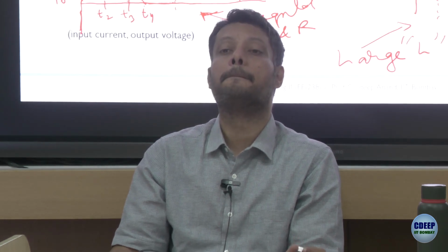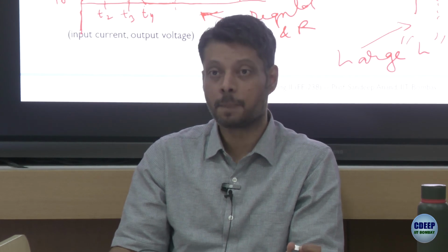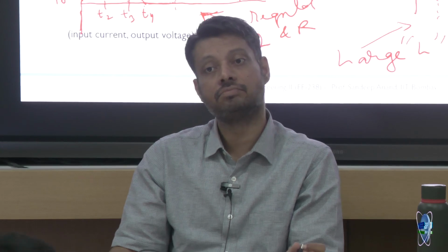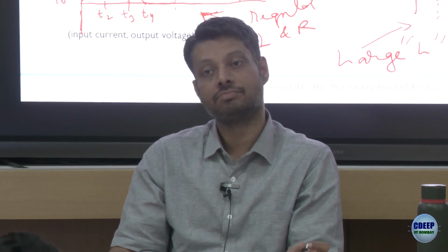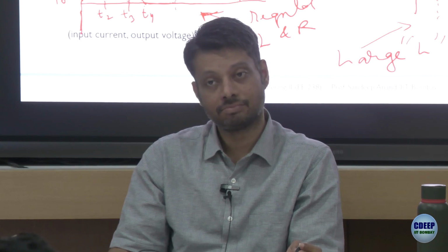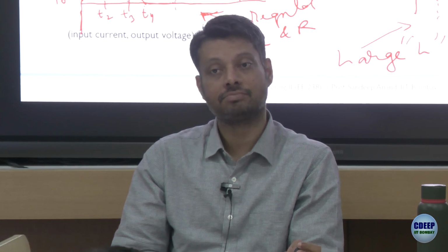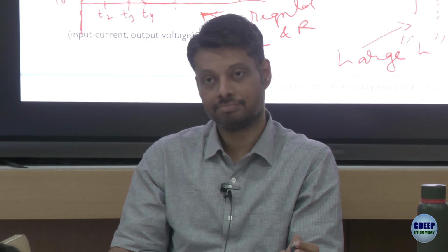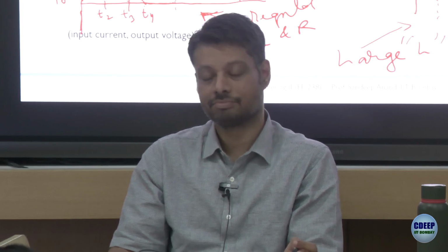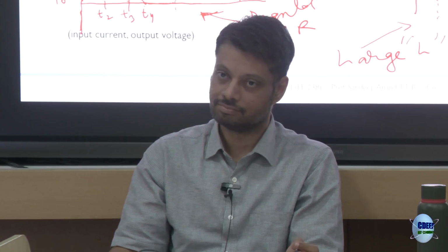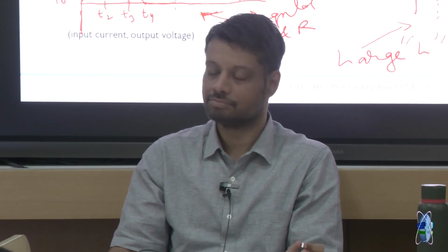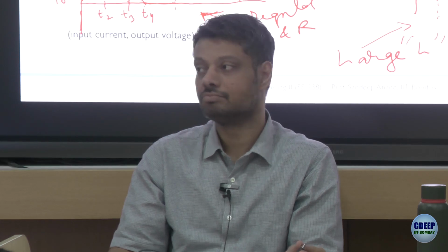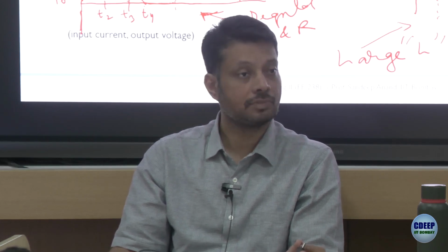Because since the voltage is following B, and it is equal to L di by dt, the slope of di by dt will be the same while rising and just the negative of it while falling. So from 0 to the halfway point, the amount it rises, it would need that much time only to fall again. So then it should end at the exact point where it started.